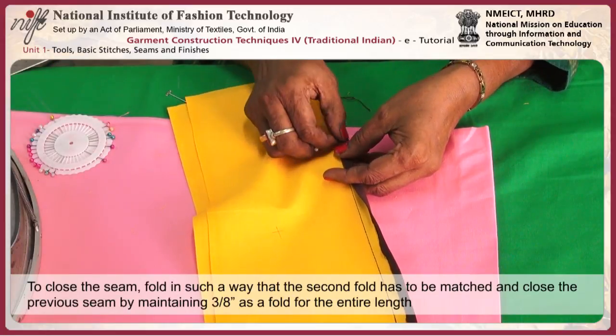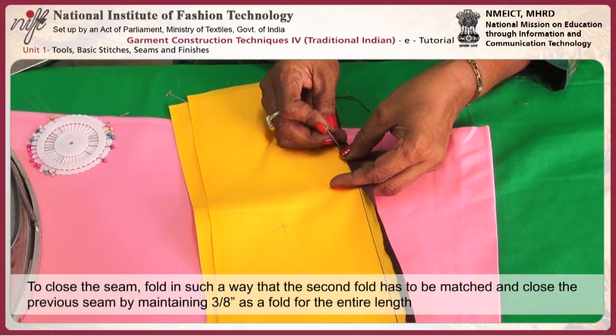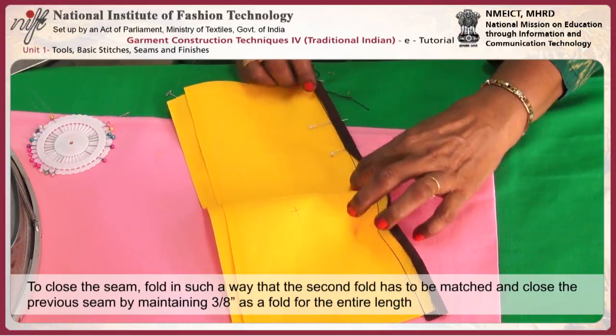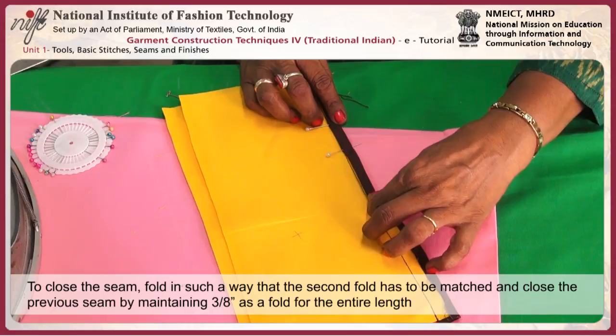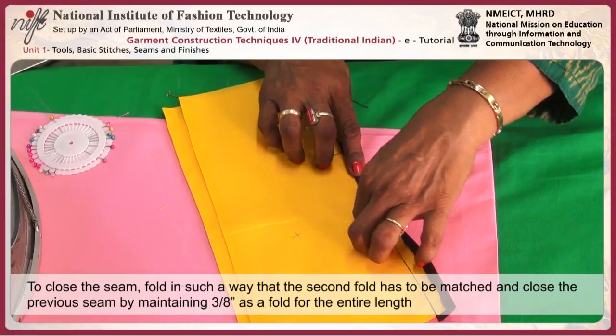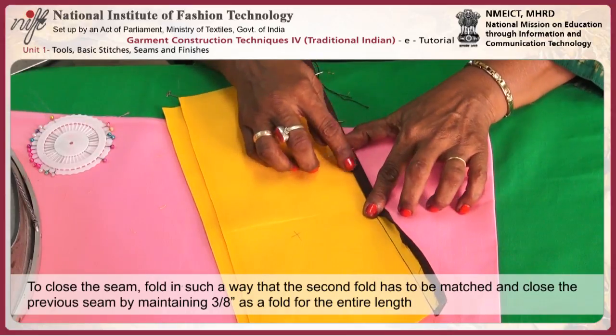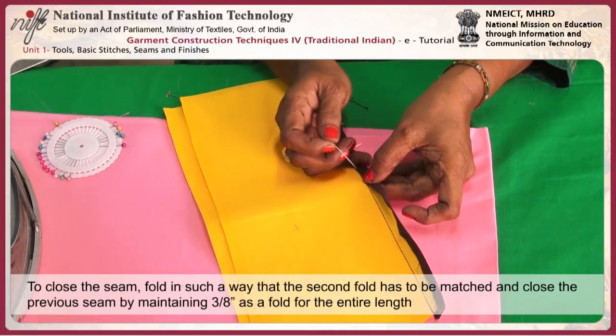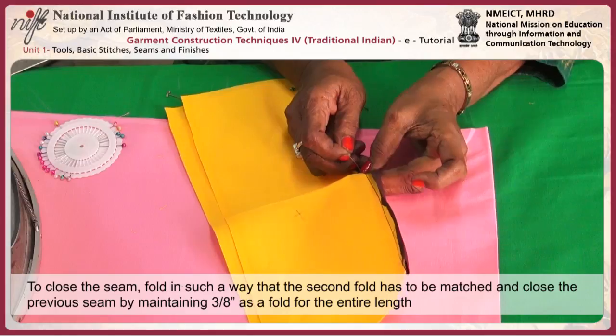And we have to close the seam. The previous seam has to be closed. Fold in such a way that the second fold is matched and closes the previous seam by maintaining 3/8 of an inch as a fold to the entire length.